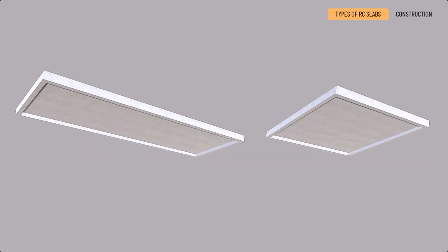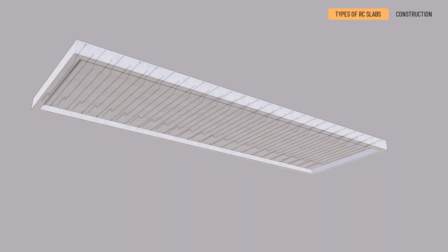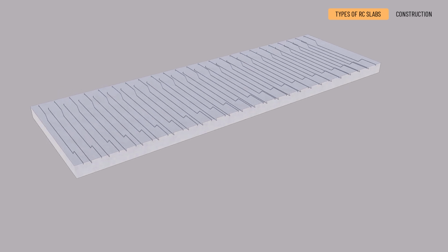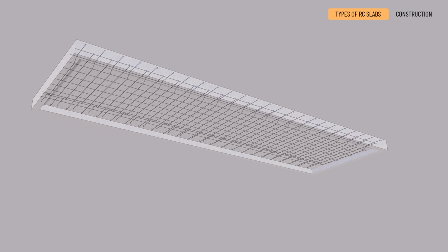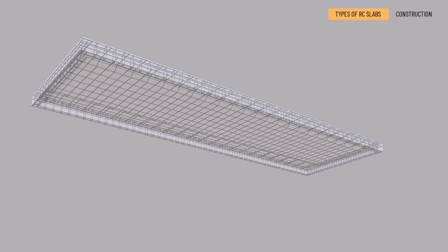Flat reinforced concrete slabs. Flat slabs are flat structures, typically 15 to 25 centimeters thick. The slabs can be load-bearing in one or two directions. One-way load-bearing slabs may cover rooms that have a shorter span, 2.5 to 4 meters. The main bars are placed in the shorter direction, while the longer direction is used only for distribution bars. The long side is primarily used for load carrying, but typically a ring beam is made on the short side too.